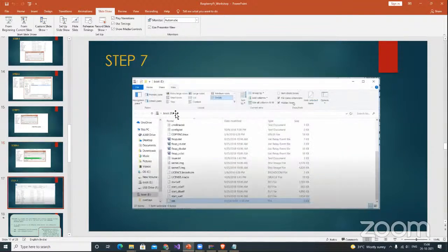And afterwards what you have to do is just open the SD card, in the boot section. It will be named as boot, and E or F or G, maybe depending upon your computer partition. Based on that, here you have to just create an SSH file, an empty SSH file. Very simple. That's great, guys.